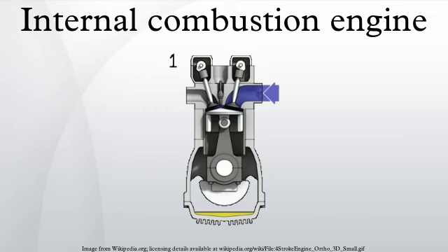HCCI-type engines take in both air and fuel, but continue to rely on an unaided auto-combustion process, due to higher pressures and heat. This is also why diesel and HCCI engines are more susceptible to cold starting issues, although they run just as well in cold weather once started. Light-duty diesel engines with indirect injection in automobiles and light trucks employ glow plugs that preheat the combustion chamber just before starting to reduce no-start conditions in cold weather.